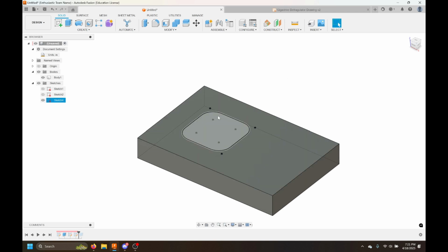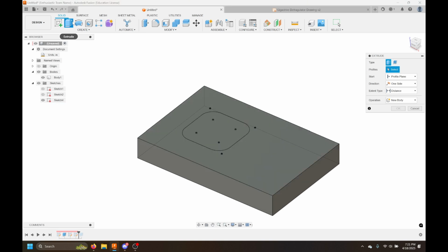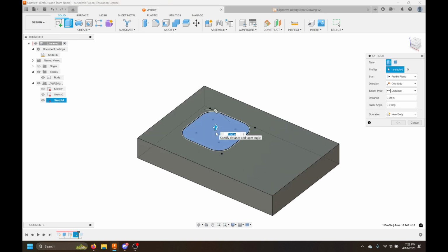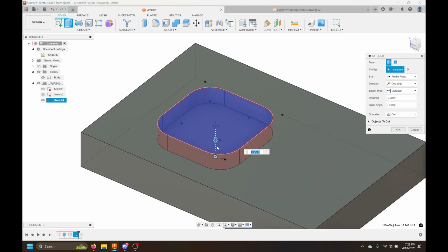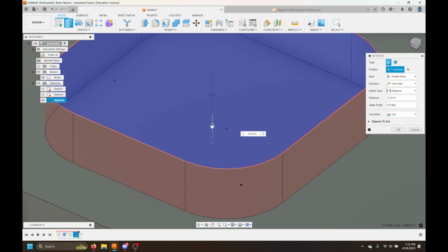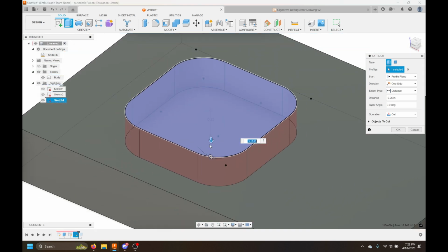So now we've got this shape with our 4 curved edges, and we're gonna extrude it in, and the depth is 0.25. So I'll grab the extrude tool, and then my face, and it'll be negative 0.25 because I'm going in. You can also drag the slider around, and it's not hitting the dimension. So if I zoom in, you can get even closer to it. Right there, 0.25.